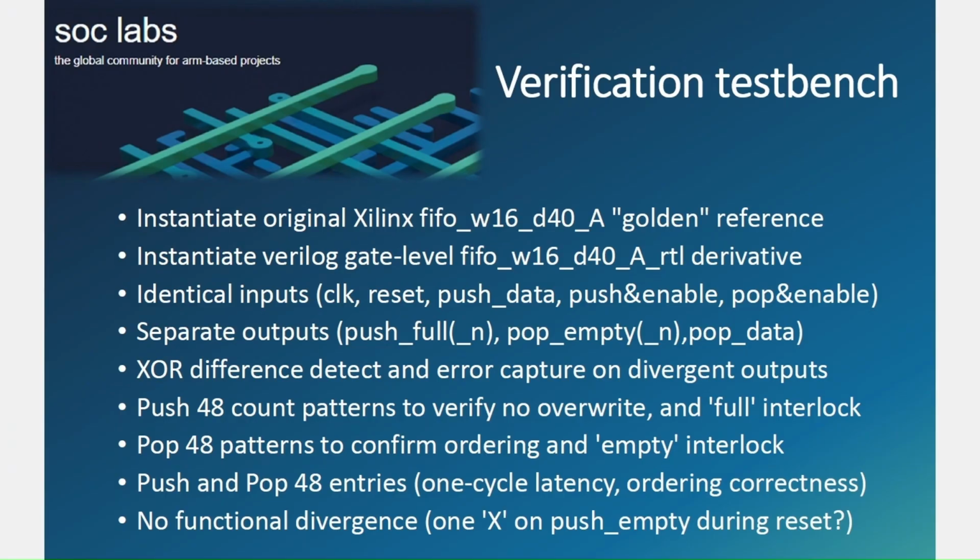The verification test bench instantiates the original Xilinx FIFO as a golden reference. We instantiated the Verilog gate level with identical input and separate output, 48 push counter, 48 pop pattern, pushed and popped 48 entries, and there was no functional divergence.